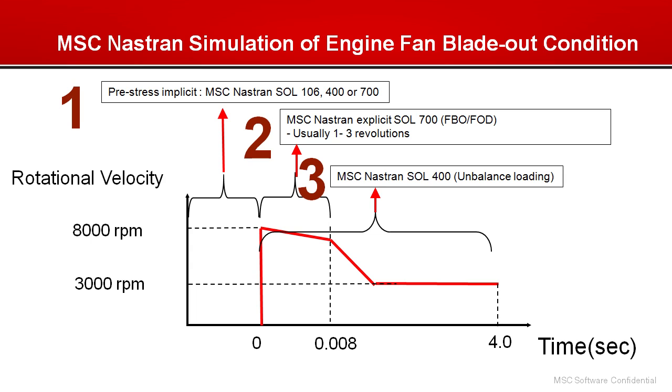And in the final stage, what we do instead, we output the actual blade out loads, thousands of transient loads, if not millions, into Nastran master database. To honor the confidentiality issues, the model information is not written to the database. So actually, the engine companies can take the Nastran database and just pass it on to the airframers without any worry. This is the Nastran database that includes the actual realistic loads passed on to the airframers.